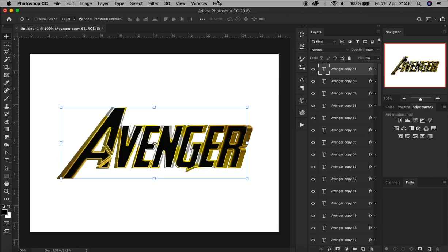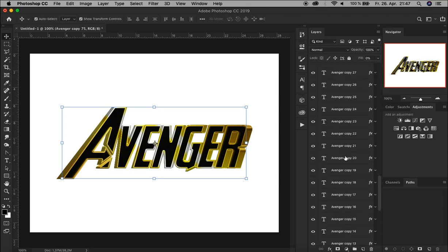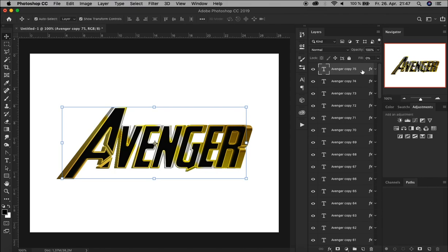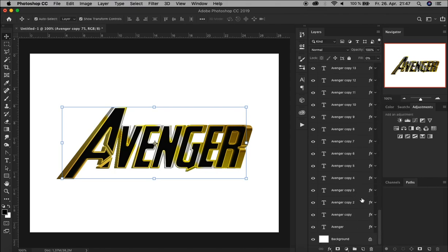Don't worry about the content turning into black. All right, I think that this extrusion is now enough. Yeah, and again, I do this a few times more actually. All right, you see we've created many layers here. And the next thing we do now is first to change the arrangement of the layers, because when we create layers like we did now, the arrangement is actually reversed, which is wrong. So let's select the first layer here, go down here to the third layer from below, which is this one.